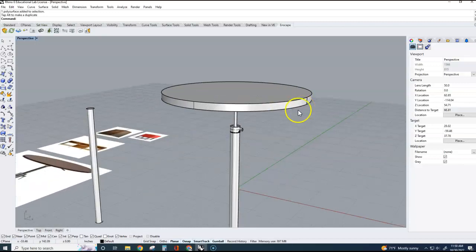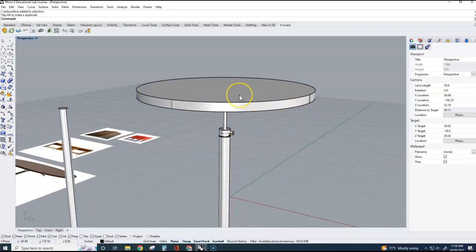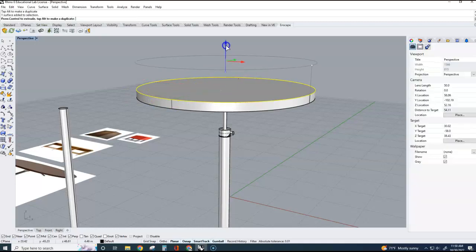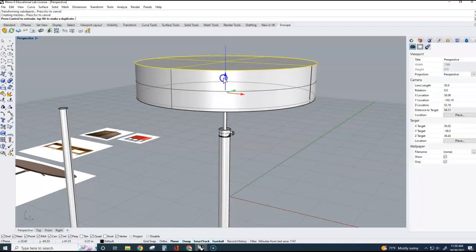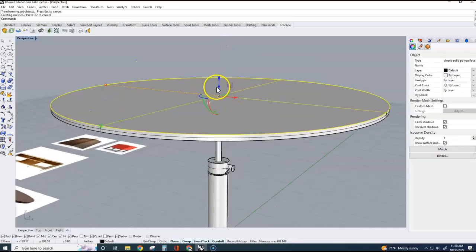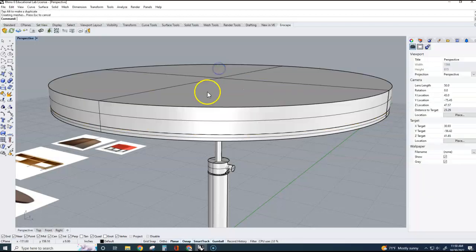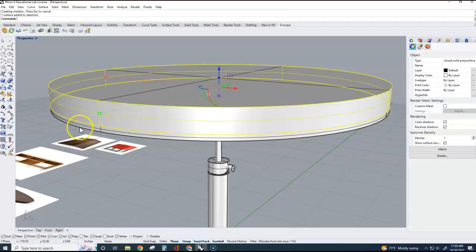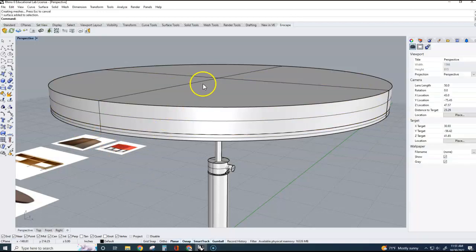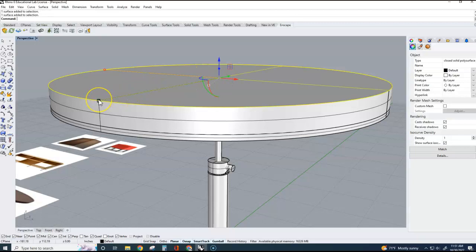You know what, before I leave though, let me show you how powerful that Control Shift tool is. So let's say I want to detail out this edge of this table. Control Shift this top. That allows me to make that chunkier or skinnier. But there's this little blue sphere here. If you grab that and you pull it up, you're going to be making a completely different face. So you see how that is separated from that? That's really powerful because now if I select this, I could scale this.